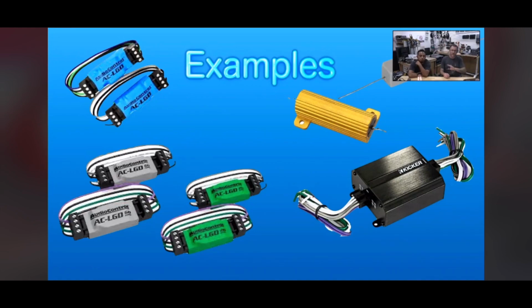Kicker said, you know what? We're just going to make one load resistor to rule them all. I like to refer to it as the load resistor grenade. It comes in a small heatsink about the size of their little bike amplifiers, and it is a low enough impedance that it will turn on any scenario you could possibly throw at it. So if you have a situation where it's cutting off or it's not working the way you want, get one of the KISS loads, throw it in there. Nice thing too is it's got a big heatsink, so you can mount it like an amplifier and everything is hunky-dory.